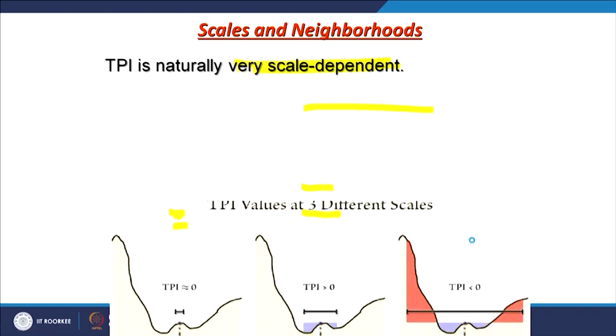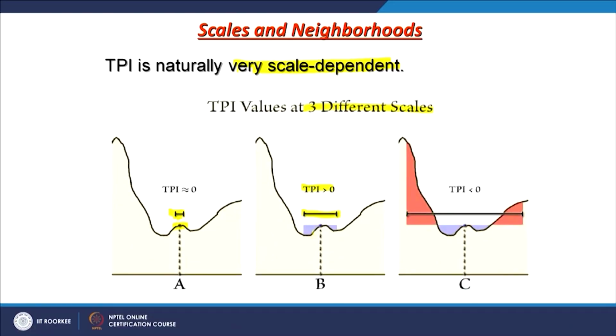And yes, it is a hilltop and ridge top. If the scale is very small and a very large area is being looked at, meaning the spatial resolution of the input digital elevation model is very coarse, then all the upheavals or topographic roughness present in the ground will not be considered, as a large area is taken. That means here the TPI value will become 0.